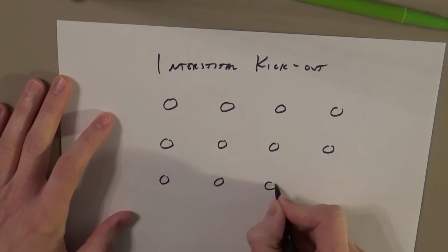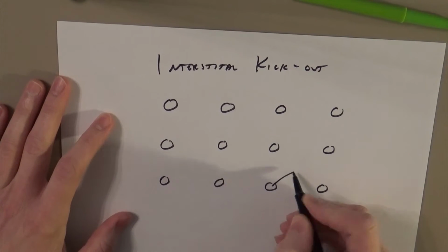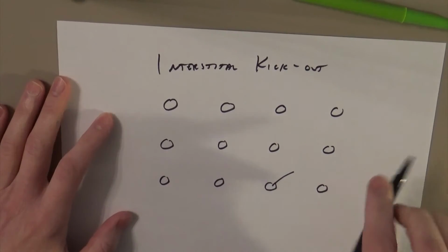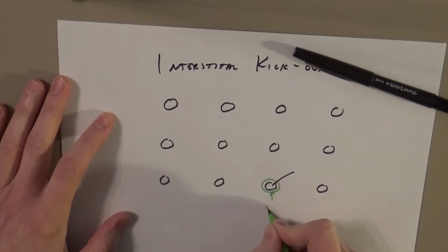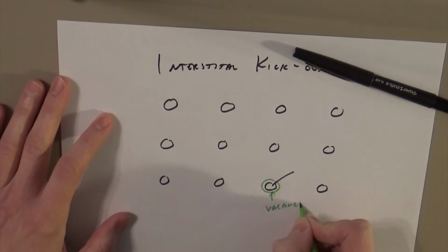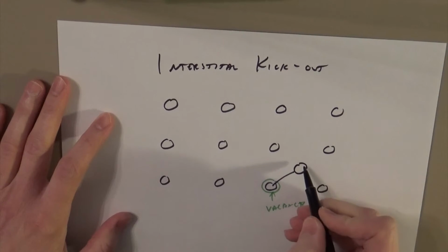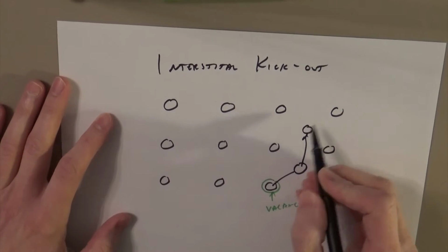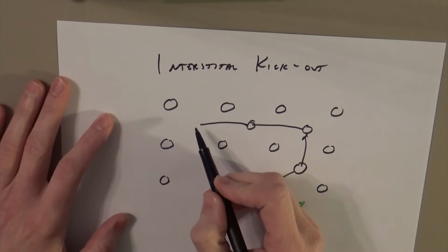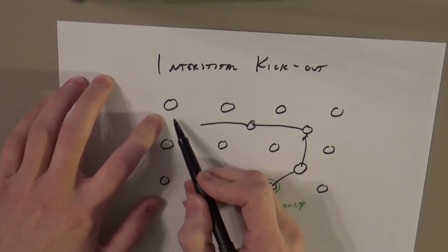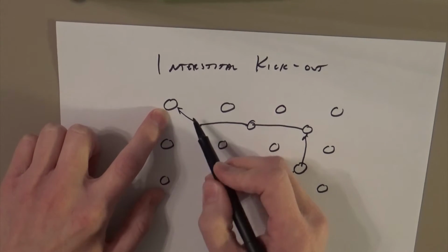Like this. And what happens is some atom goes off its site. So now there's a vacancy here. I'll put an empty spot here. Vacancy. And now it's sitting in an interstitial site, and now it will diffuse through interstitial sites. And it will either come to a site which is vacant, or it will come to just another site and it will kick that atom out.